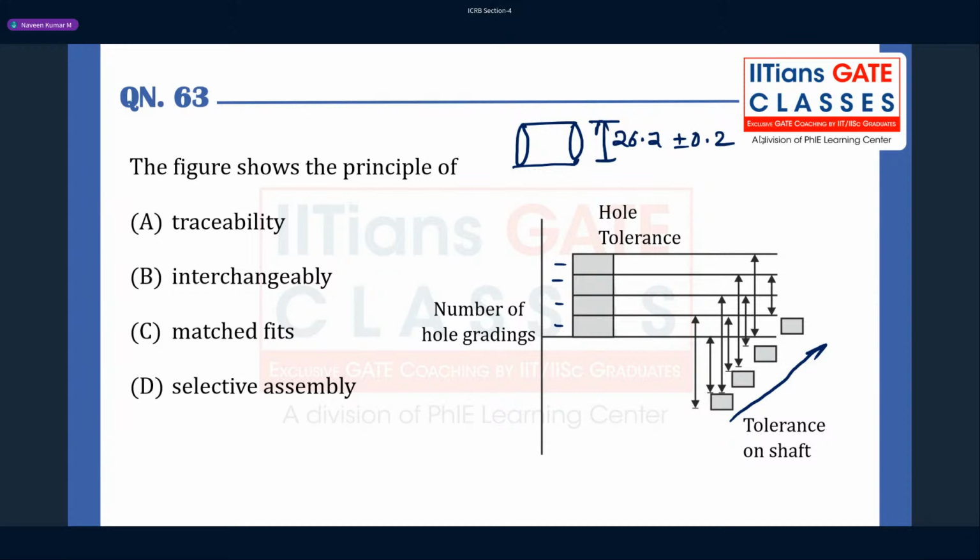So you have to do calibration properly. What is calibration? Before checking what you have manufactured, there are some standard specimens. The standard specimens already have some fixed diameter, right? When you are measuring with your vernier caliper or screw gauge, obviously it has to give whatever diameter the standard specimen has. So that is what calibration is. You do the calibration first, and then you see that yes, the equipment is perfect. Only then use that device for the product that somebody has manufactured.